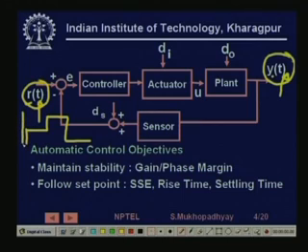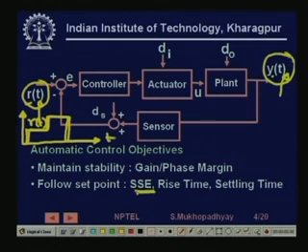So this is a typical R(t) and this is y(t). So they take step jumps, again are held. So we are typically talking of this kind of step responses, this kind of set points. With respect to this kind of set points, to express the degree of accuracy with which y can be close to R, we express various quantities like the steady state error, rise time, settling time, etc.